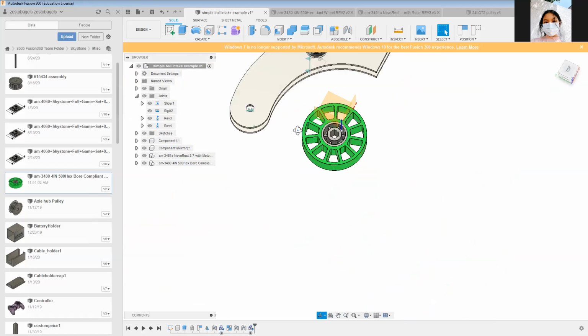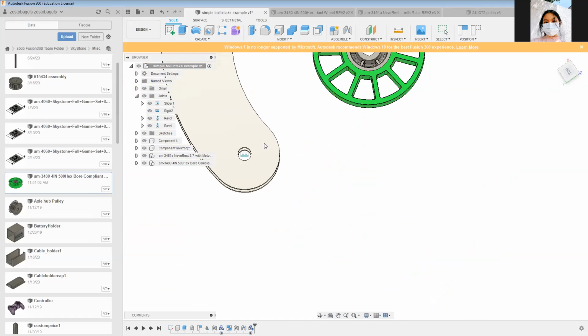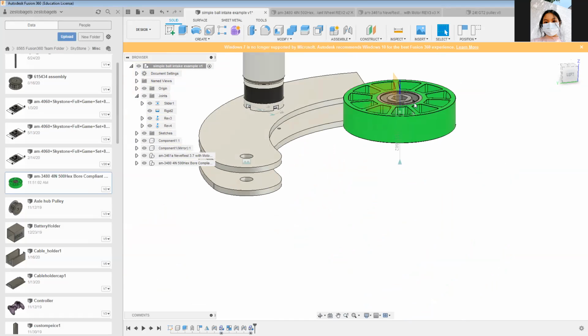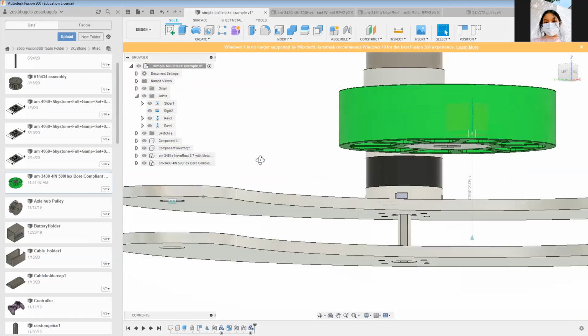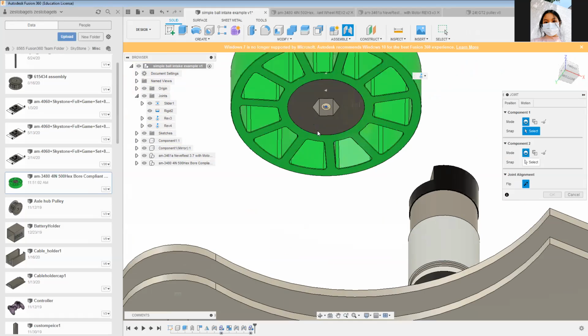So what I'm going to do is, this is going to be a normal REV 5mm hex shaft, but then REV also has Ultra Hex, which converts the 5mm hex to 1/2-inch hex. So I'm going to pretend I'm putting one inside this bore. So now it's a 5mm hex bore. I'm not going to actually model that right now, just for the sake of time.